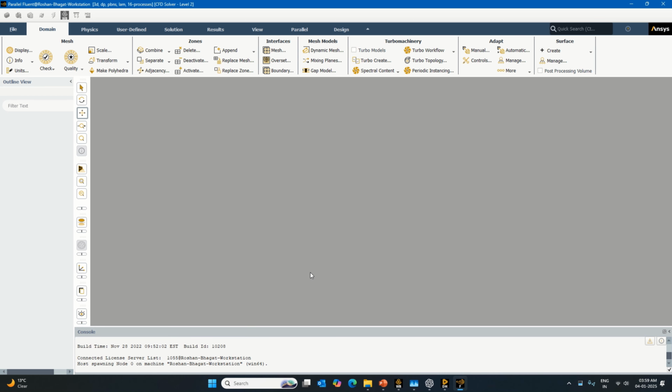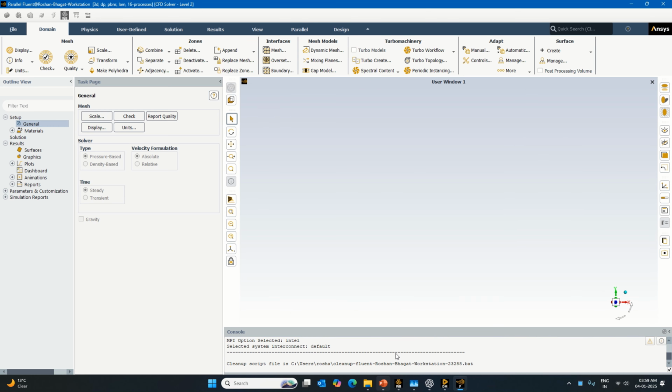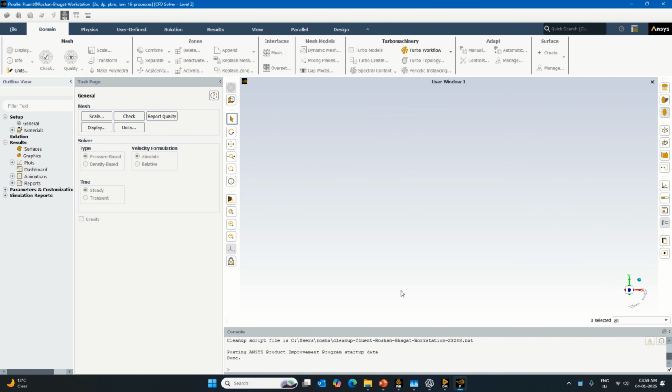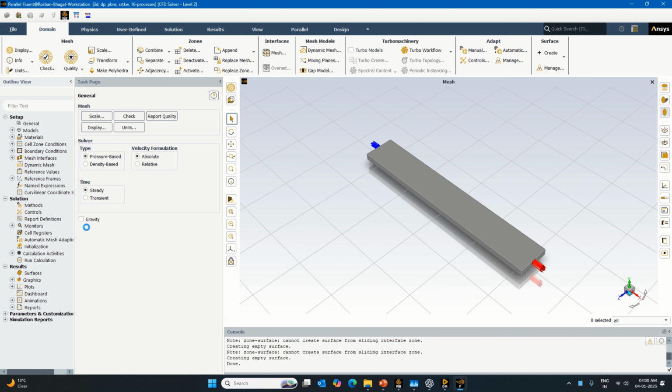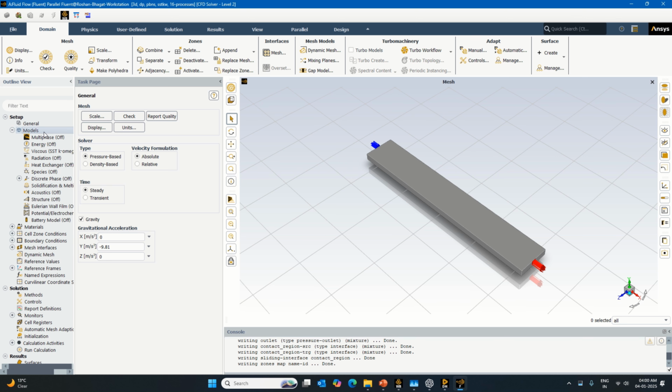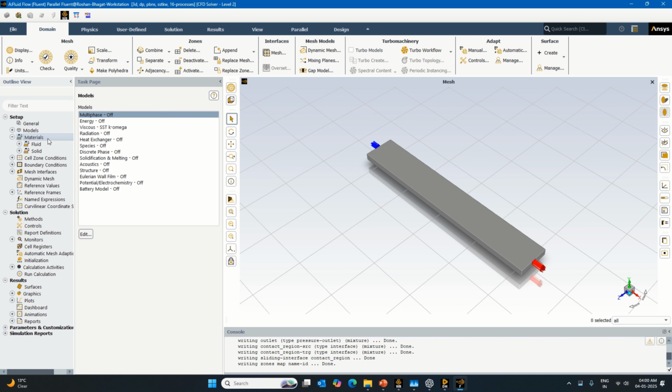Depending on the models now, which model you are looking for, whether you are looking for a cooling model or we are just interested in the fluid flow in Fluent, accordingly the respective models can be selected. Here I am still going with the steady option, but if temperatures are involved, you can go with the transient option also. Gravity is the same, that is minus 9.81 here. So this model also I will keep as it is.